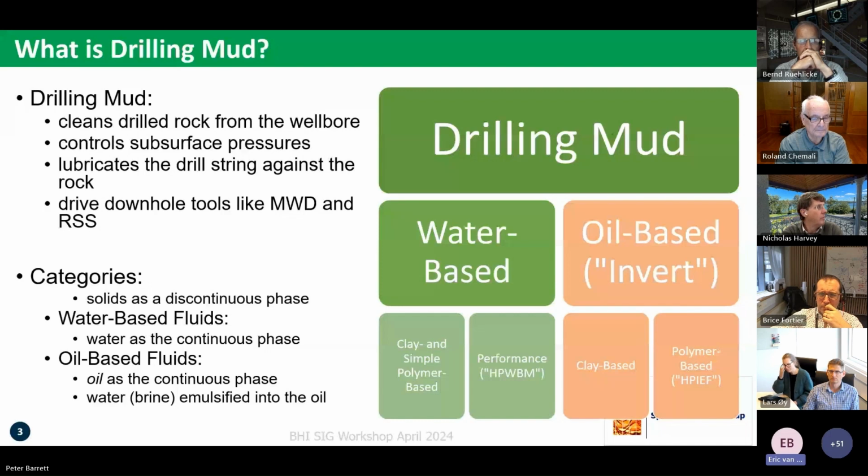We may further separate water-based and oil-based muds into old-style clay-based fluids and the more modern high-performance ones, which are largely polymer-based and where there's much stricter control of quality and solids content, just to speed up the drilling process.